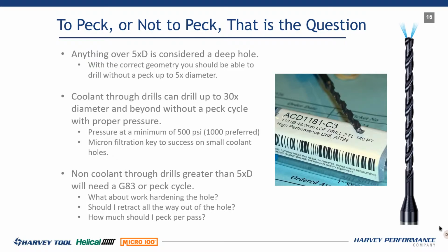The next question: should I retract all the way out of the hole? So we're talking about 5 times D and greater. I'm not talking deep hole drills. Let's stop right around that 12 times D, just for grins here, just to keep it on a regular basis, 5 times to 12 times, which is pretty common in drilled holes. All right. So should I retract all the way out of the hole? Yes, my opinion is yes. Take that drill and come all the way out of the hole.